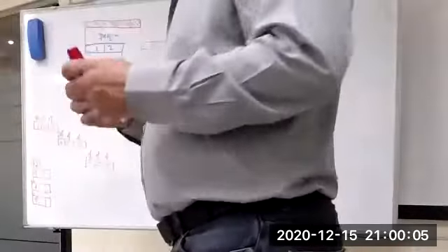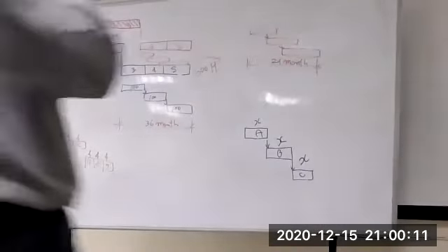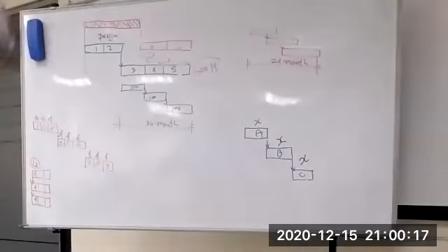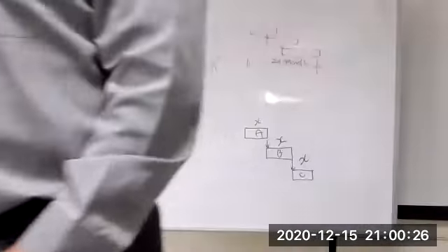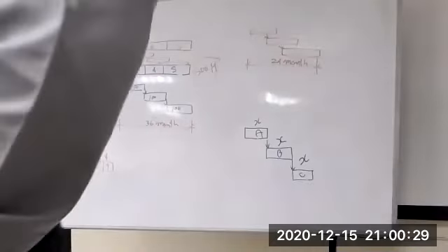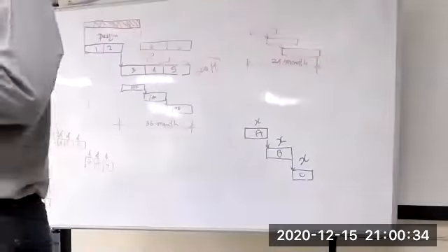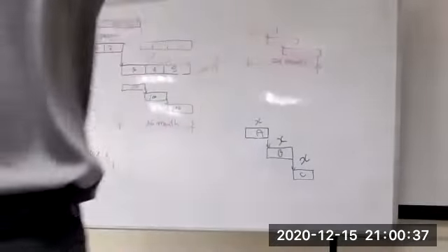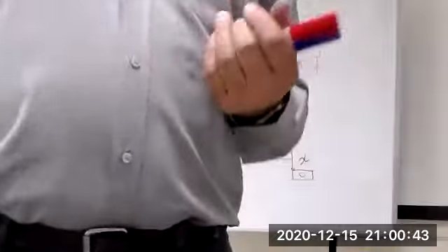When you are exercising with purchase or lease or rent, when you have such a technique, you check, for example, the scaffolding system. What is the optimizing, how to get the efficiency of using this shuttering system through leveling techniques. Limitation of your resources, how to get the efficiency from the limitation of your resources. You have limits. You have one excavator, two excavators, a skilled labor, a skilled steel fixer, you have steel, and you have a bar bending fork. How to segregate them into the activities so you get the efficiency of their production rate. This is what we call resource leveling.